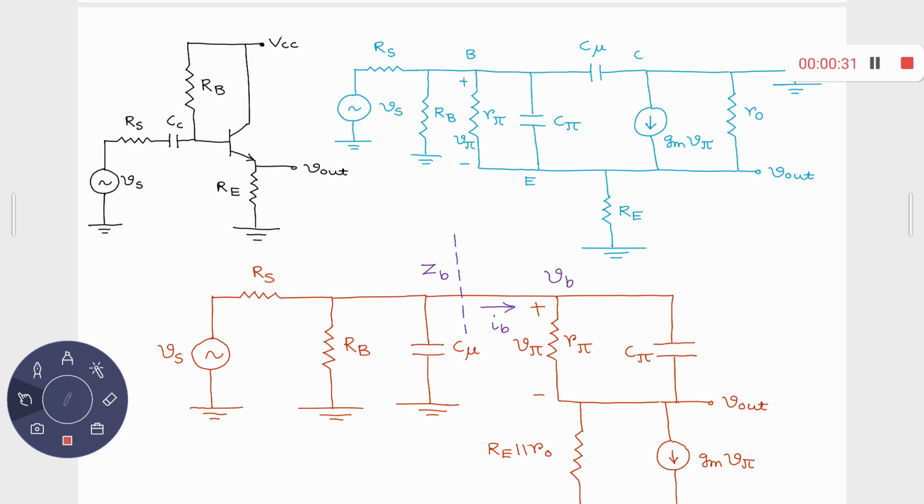And you have noticed that whenever we use this common emitter common base cascade, that particular amplifier will give you a moderate gain with moderate bandwidth that you cannot get using a single isolated common emitter or isolated common base amplifier. So that time I told you, and you can also remember, that we did not go for this extensive calculation. We identified some input RC circuit, identified some output RC circuit, and from that you found the value for this higher cutoff frequency, f_H.